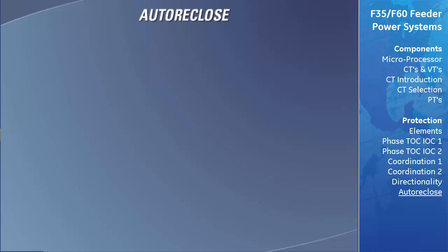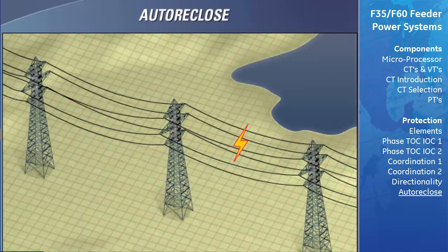If lightning strikes the conductors of an overhead feeder, or a strong wind causes 2 phases of the feeder to touch, an arc will be formed. The arc ionizes the air and turns it into a conductor. The arc is then maintained by the power being supplied to the feeder. This is an example of a common source of an intermittent overhead feeder fault.